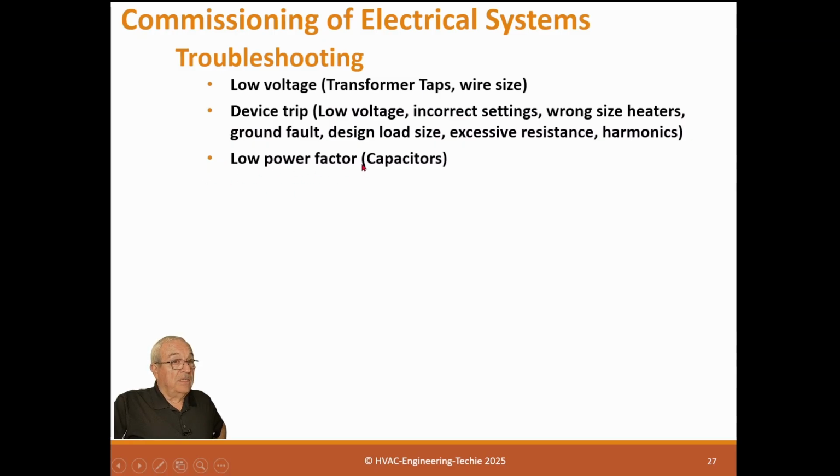Now also, a power supply in a computer, like a VFD or a computer, will actually add inductive load. And also LED lights. We used to never worry about lights because they were incandescent or fluorescent. They're resistive loads. But the LEDs do have power supplies in them and can provide that.